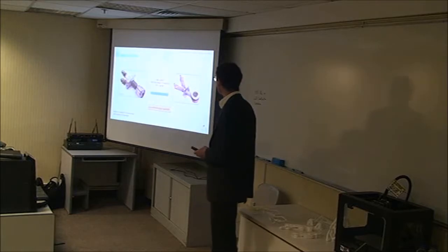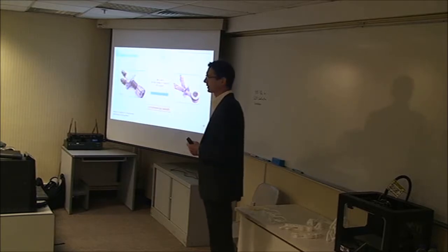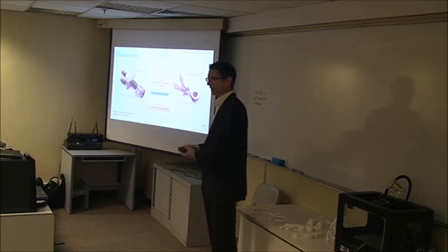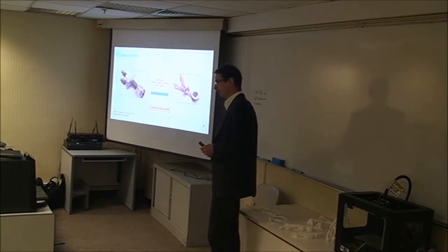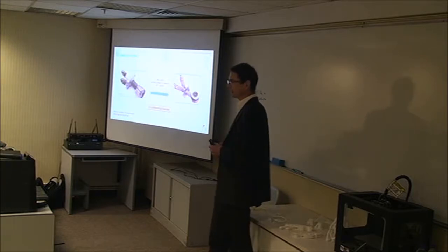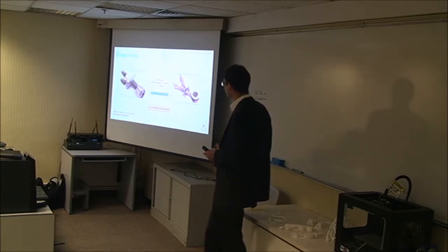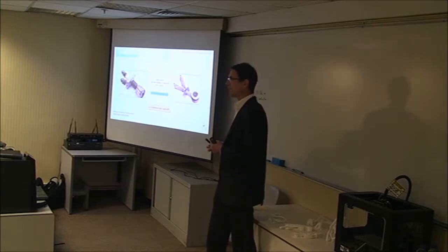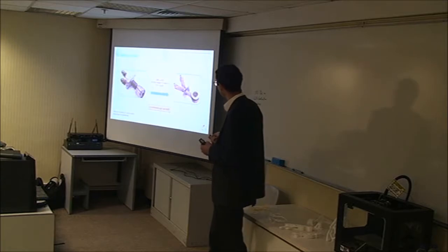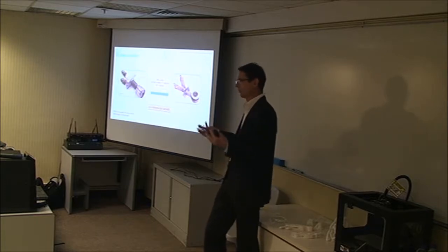And then another example, by General Electric, an aircraft engine. The fuel nozzle, you see it a lot in the press, on the internet. It is a 3D printed part in their aircraft engine, and it's a very complicated structure and geometry. The advantage is not only that it is lighter, but it combines a lot of parts together. You do not have to assemble these nozzles out of a lot of different pieces. You just print it in one piece.